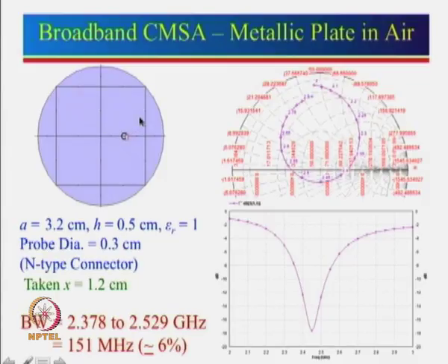Then there is another thing: a metallic plate will have some thickness, which let us define as thickness T. We cannot have a metal plate of 0 thickness. Of course, we can think about taking a thickness of, let us say, 0.1 mm, but a 0.1 mm circular disc will not remain stable, it will start warping and it will actually come down. So, instead of using 0.1 millimeter, we can use 1 millimeter thick, or maybe 2 millimeter thick or half millimeter thick.